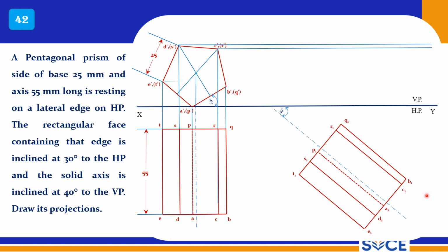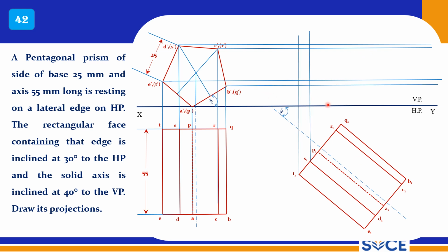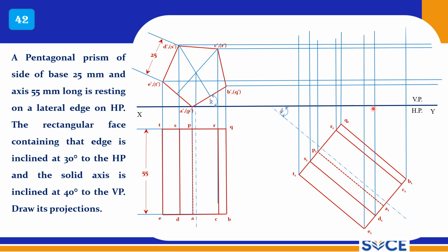Now corresponding points you can project here as we did in all other problems, right? So mark all the points on both sides, and connect all outermost points with thick lines, and here R is here, S is connected to R, so that should be a dotted line. R is connected to Q, that should be a dotted line.